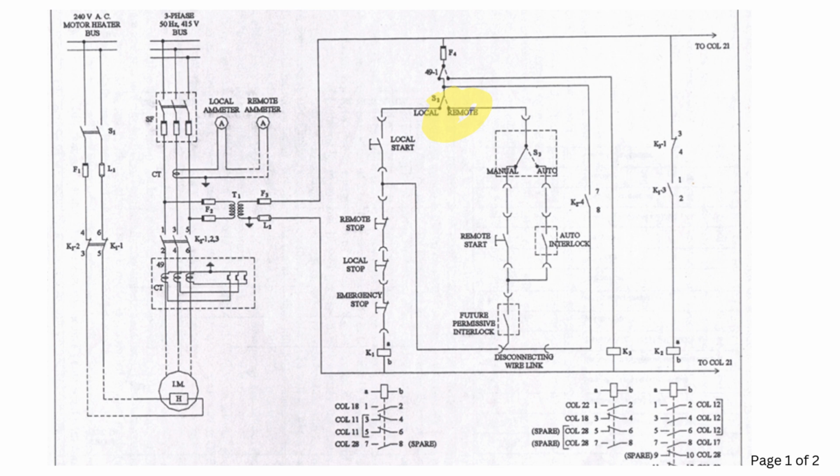The local refers to the motor's physical installation site, while the remote refers to the location where the 415-volt switchgear is installed, meaning the control room. Normally, the switchgear, or you can say the control room, is located at some distance from the motor, which is inside the plant. For example, a steel rolling mill, or let's say some cold storage farm, where the operators are not normally available beside the motor because it's a hot or cold environment.